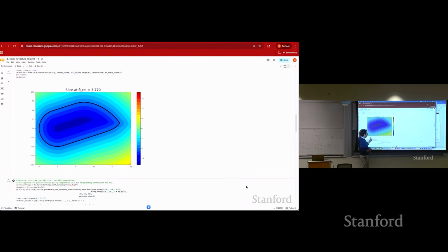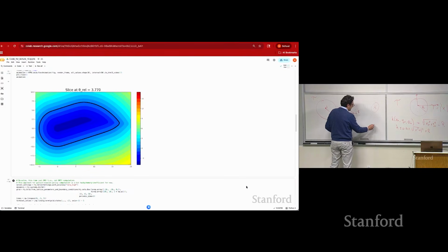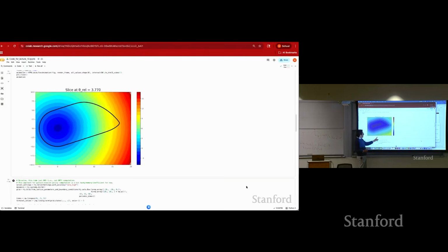X is still the notion of longitudinal distance, Y the notion of lateral distance. So we're fixing the relative heading at a little bit more than pi. The vehicle, vehicle B, is pointing in this direction, and then you want to understand where it should be placed at the beginning to make sure that we do not incur a collision. So fix the longitudinal separation equal to 5.